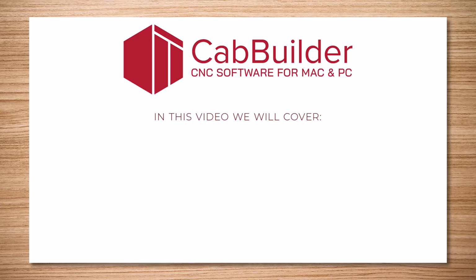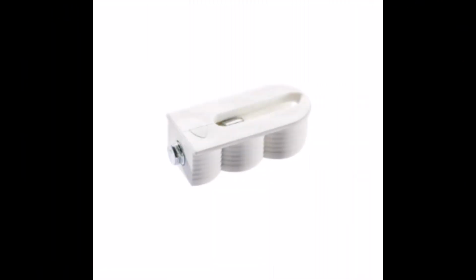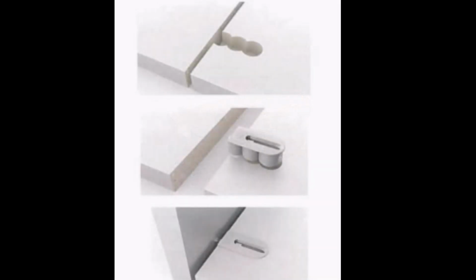In this video, we will take a look at how to create and configure a Lamello Cabineo connection construction in CAD Builder. Cabineo connectors can be useful for shops using a standard nesting router CNC because the required machining can be completed from the face of the panel without edge drilling.